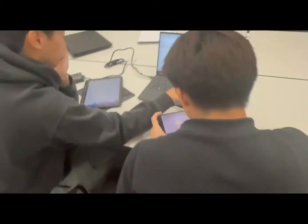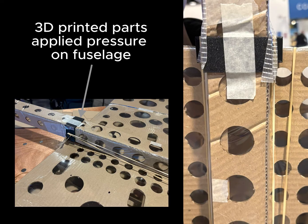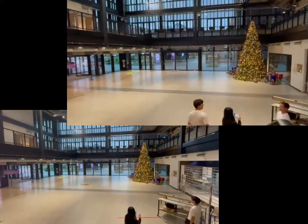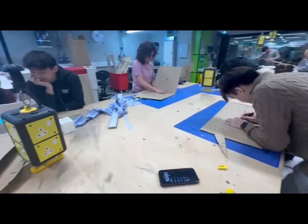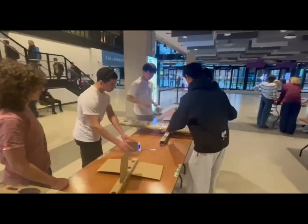We were limited in our experiments due to the frame rate while capturing our slow-motion videos, hasty and non-ideal manufacturing conditions, and structural fatigue between test flights. As an experimental finding, we found that the fuselage was bending after several flights. That revealed the limitations of our initial modelling and manufacturing imperfections, as deformed structural parts increased skin drag and losses over time.